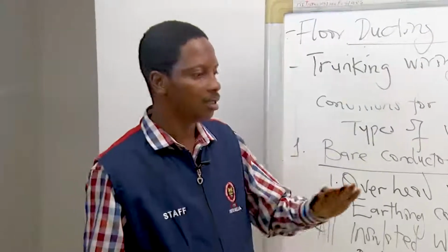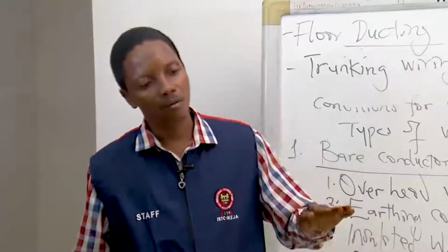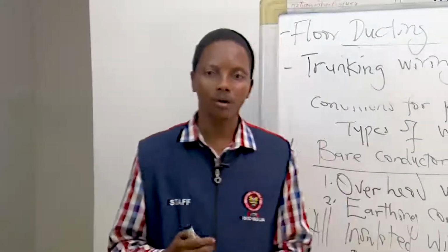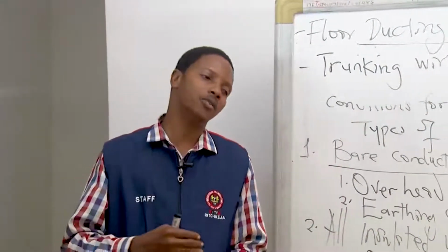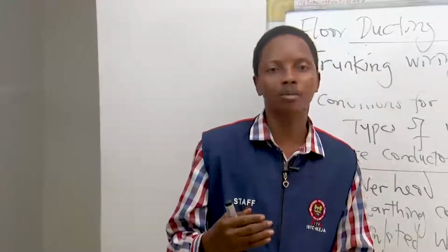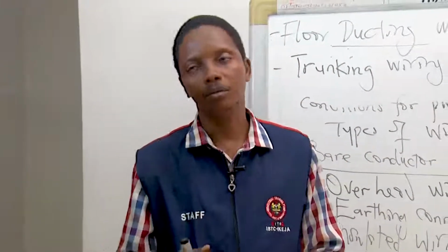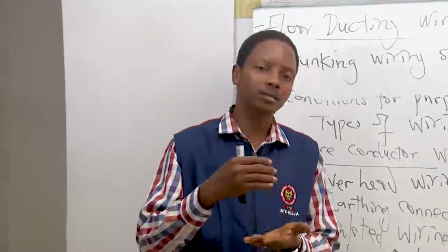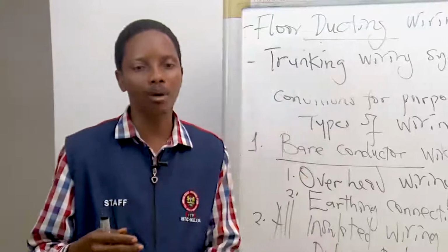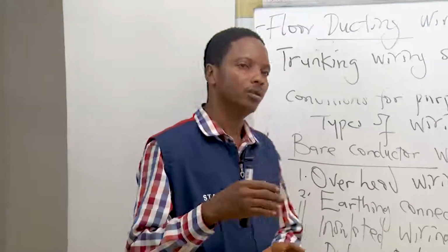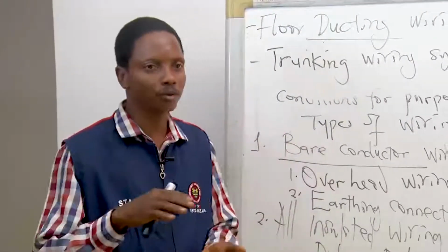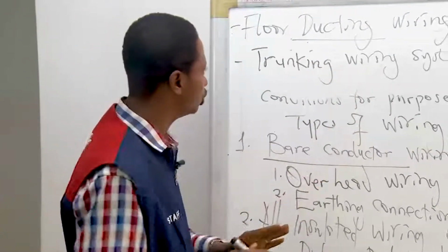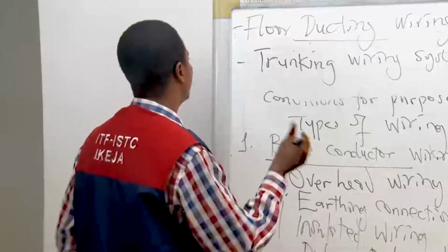You will see the level of sockets from the floor, mostly from 300 mm above ground level to a maximum of 600 mm. And then for our switch, from 1,200 mm above ground level. So you can see all these things, we have to keep to standard for all the arrangements. So these are the things that come to play.